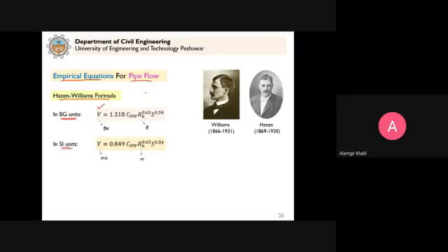And in the Colebrook equation, F was present on both sides. Essentially to calculate F, you do a trial and error. And if you have, let's say, 500 pipes in the problem, 500 times you have to do the trial and error. So it was very time consuming.